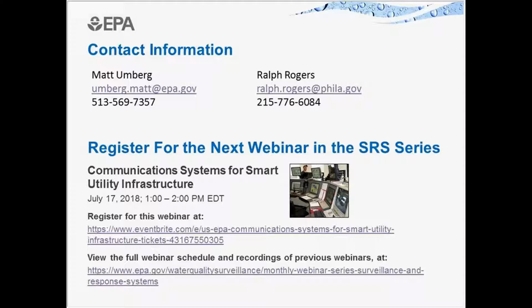Online water quality monitoring in the distribution system doesn't have those reporting requirements yet, and I know that some of the smaller utilities, for financial and budget reasons, would like to use a sensor to replace grab sampling, but I just don't think the technology is there yet, in my opinion. As you can see, there's the level of effort that we have just going through the data management and detecting false positives and whether it's a real event. So you just can't put a sensor in and walk away and say, okay, I'm going to use that value. It's a very complex question to answer.